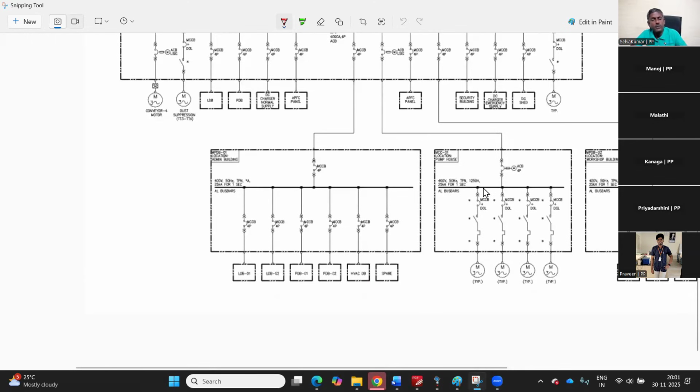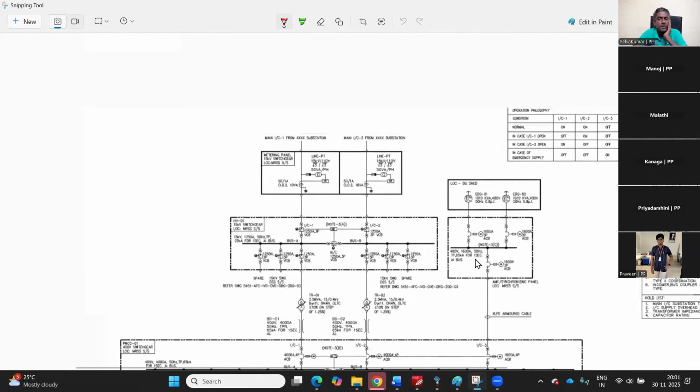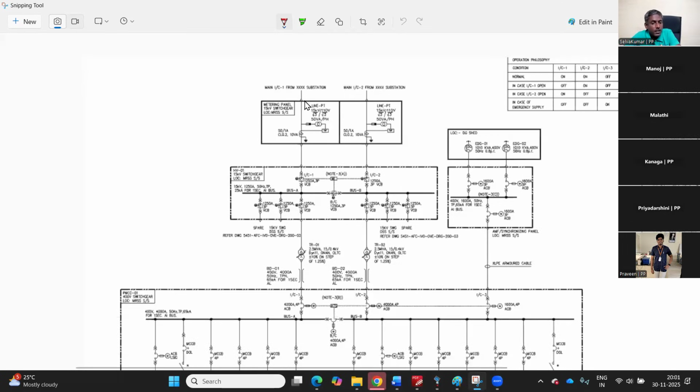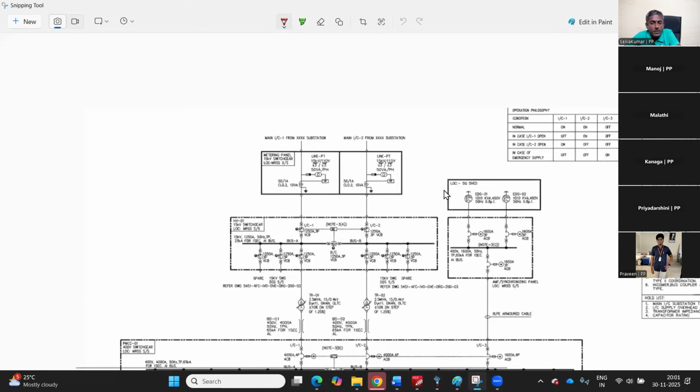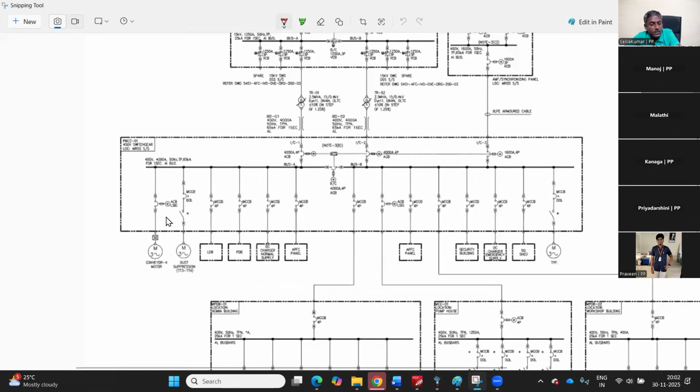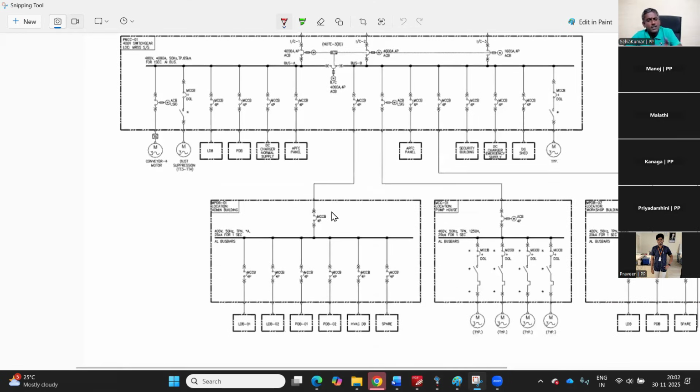It's a very simple project, but even for that you can see there are multiple packages: metering panel at 15 kV, 15 kV MV switchgear, transformer package, LV switchgear package, diesel generator package, synchronization panel package, motor package, distribution boards, power factor correction capacitor packages, and so on.